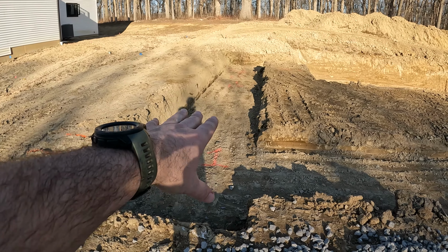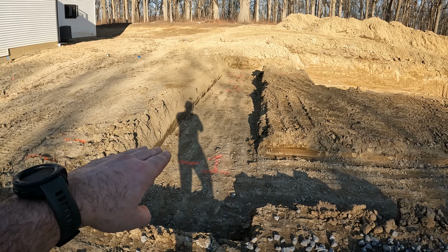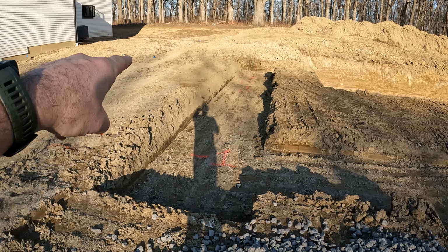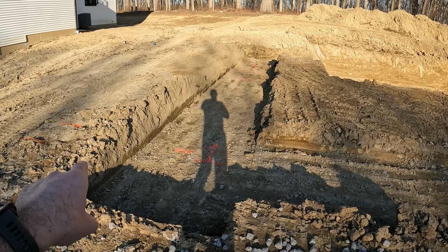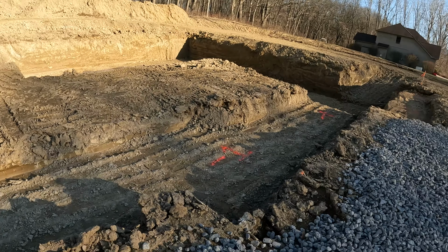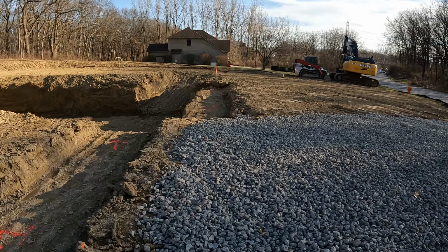If we were to pour on top of this and match the elevation that the engineers called for, this front corner of the garage would be about 2 foot higher than that one. You're going to end up with a steep grade, but you can't just drop one thing a foot. When you change something in a foundation, you have to look at everything that it can affect. When that corner drops a foot, the garage floor drops a foot, which means the driveway drops a foot, which means you have to figure out what you're going to do with your porch.